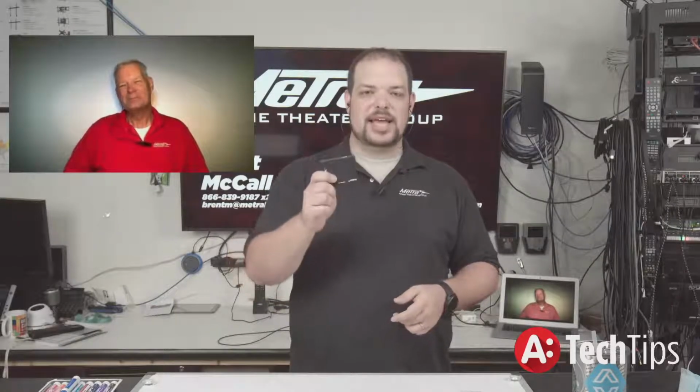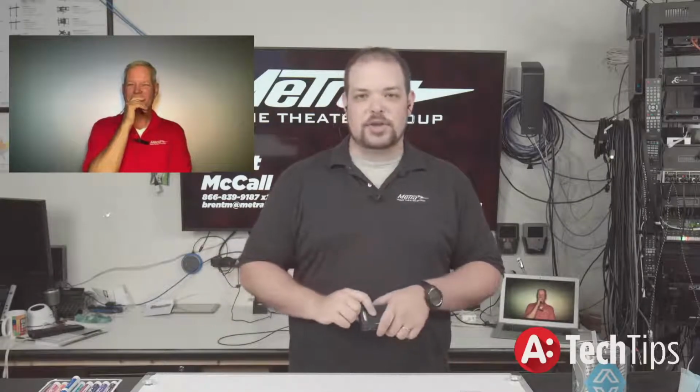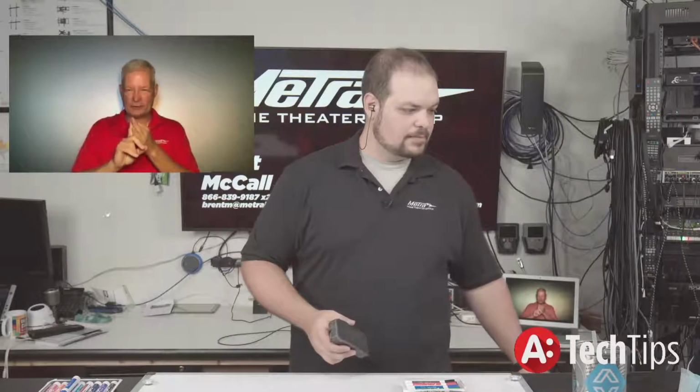Yep. So with that, go ahead. If you are still having troubles with it, of course, give us a call on tech support. We're happy to help out with it. At that point, though, we're going to ask you to please turn off CEC on any device, not just the display. Turn off CEC on your AVR if you have it on the input of an AVR. Turn it off on other devices as well, just to ensure that we don't have anything else telling the ABO3 to turn off. That's what's happening with that. One of the things at the very beginning of HDMI we used to preach is select one resolution, only one resolution, never select auto. Turn off CEC, keep your connections to a minimum.